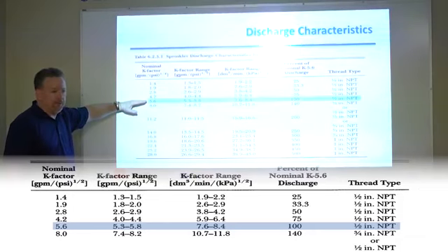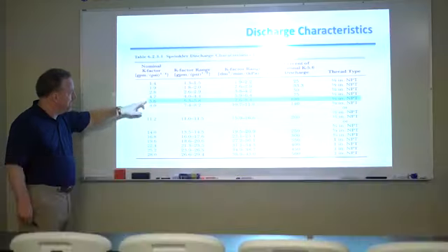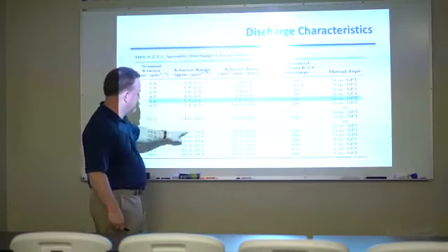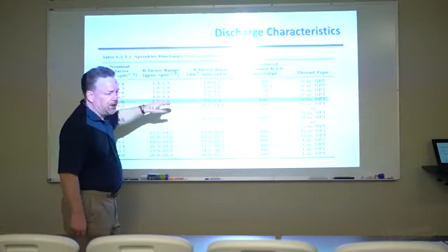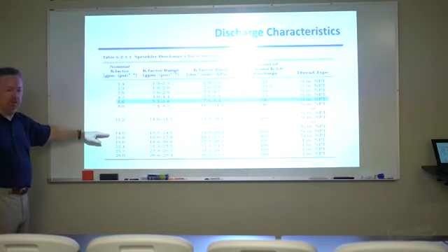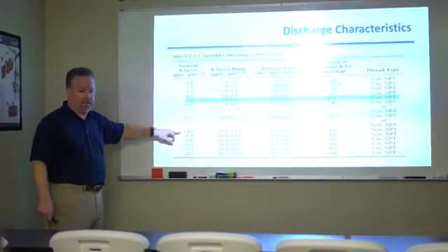Now we also looked at a K14 sprinkler on that last slide. Taking a look at a K14 sprinkler, as opposed to this, 250% of the flow of this particular sprinkler can flow out of a K14. A lot more water can flow out of that. More than 2 times the amount of water, 2.5 times.